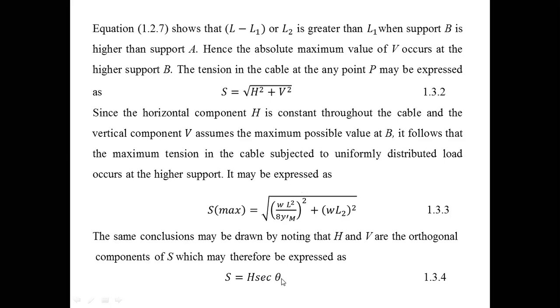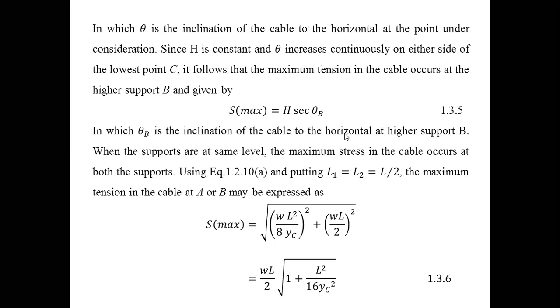Already I will explain in the first problem. Therefore, S max is equal to H secant theta. If the supports are at the same level, S max is WL square by 8yc, and the vertical reaction is WL by 2. Then S max is equal to WL by 2 into root of 1 plus L square by 16yc. This is for supports at the same level, subjected to uniform distributed load.